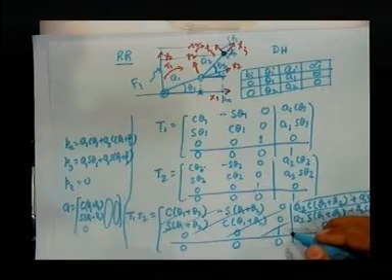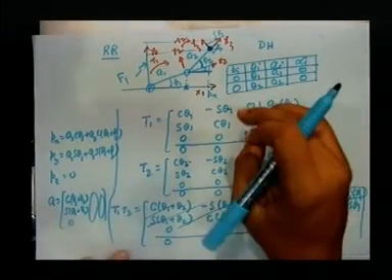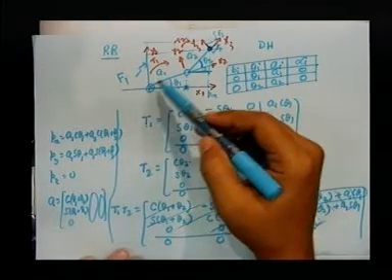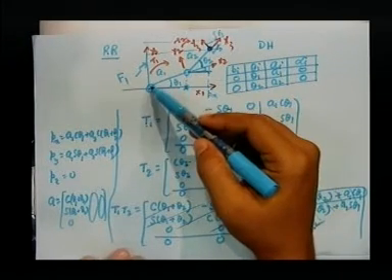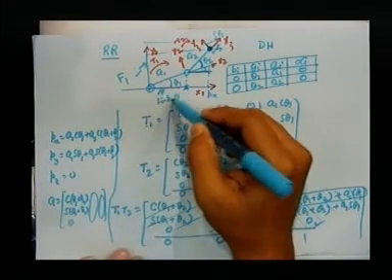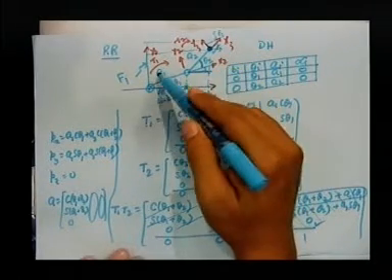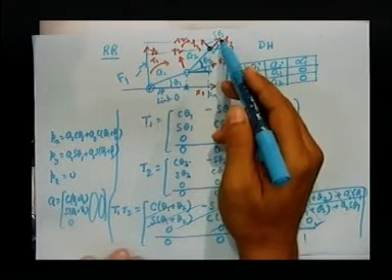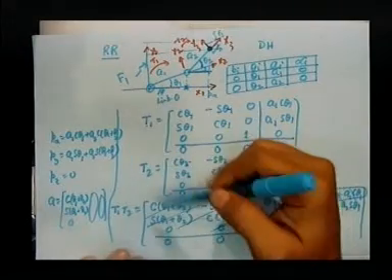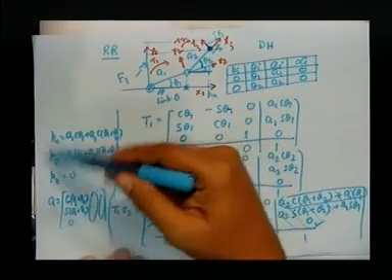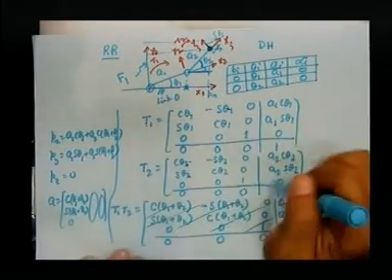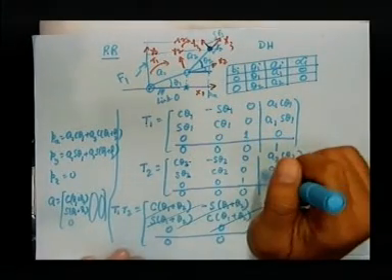So, what I have shown you here is a systematic approach of multiplying the transformation matrices between two links, here between link 0 and 1 first, and then 1 and 2, and then if I multiply those matrices, I get the relationship between the last one and the first one, which I have done in this portion. And to show that this is done correctly, I have used my earlier knowledge of coordinate geometry and proven they are rightly done. So, whatever we are doing here is right, and we can continue doing it for more complex systems.